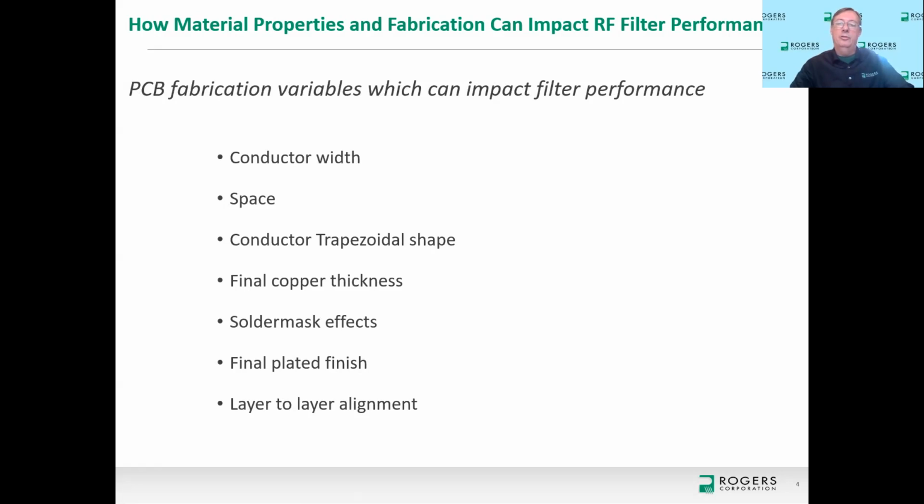And the copper thickness varies usually because it's a plated through hole circuit, and plating the copper through the hole also means that the circuit image gets plated thicker or thinner along with that process, and there is normal variation for that copper plating. So conductors can be thinner or thicker from one batch to another of the same design, and that thickness does have an effect on the trapezoidal effects and does have an effect on coupling, especially if it's a tightly coupled design. So again, a wideband RF filter with tightly coupled resonators, then the trapezoidal effects as well as the copper thickness variation can be pretty important.